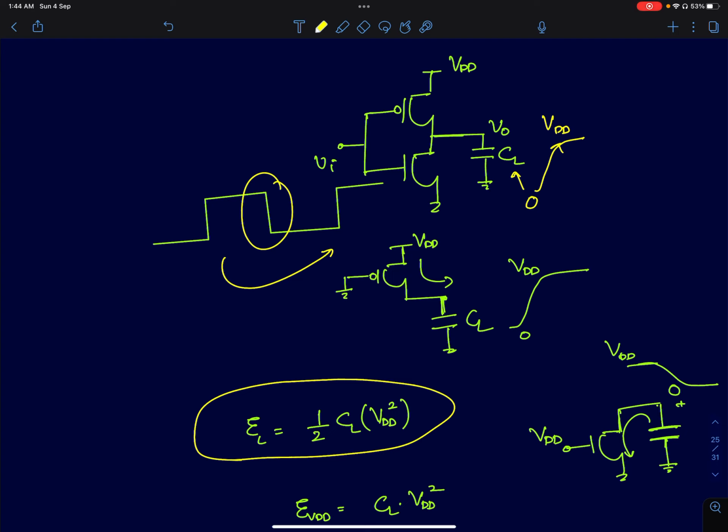We also discussed that if this charge is being supplied by a constant DC voltage source through a lossy resistive path, then half the energy will be lost in the resistor itself. It doesn't matter what the value of the resistor is. Now in this example, it's a MOS resistor; your MOSFET, the PMOS, will be in the linear region, and that's the charging path for the capacitor. Even if the resistance of the MOSFET is non-linear, it doesn't matter. The energy that will be lost will be equal to half CL VDD squared in the resistor.